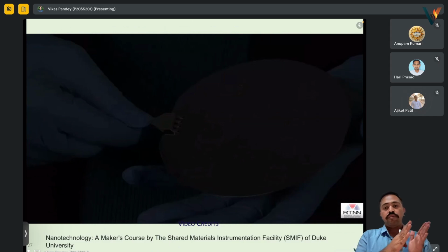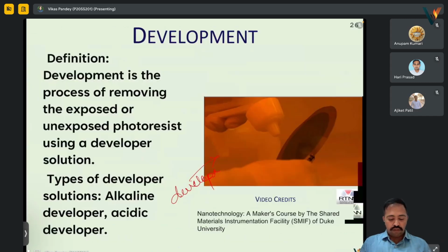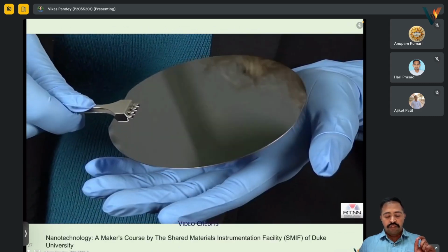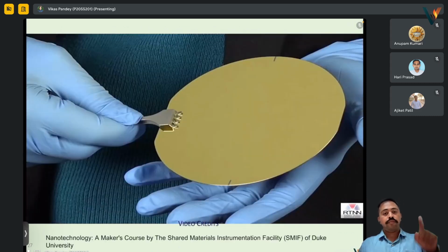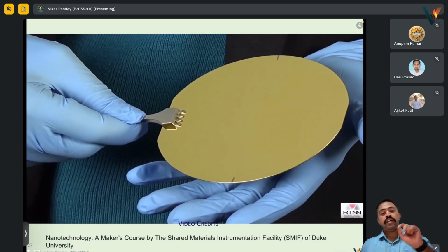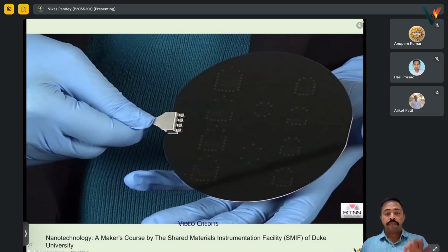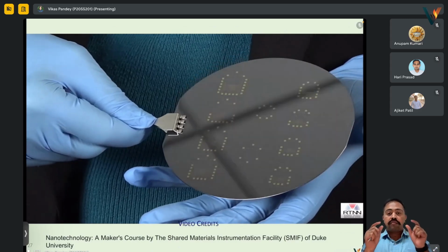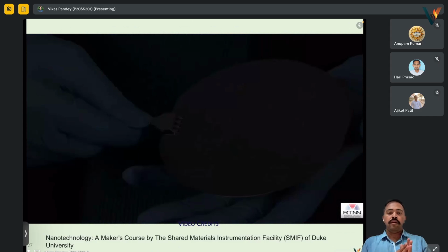Now you saw the difference between all these three. One, we had a clean wafer. We start with a clean shiny wafer, we coated it with some material of interest, then we did lithography over it. After lithography, we only have the pattern of the material we coated. Other parts are clean. This is the simple process of lithography.